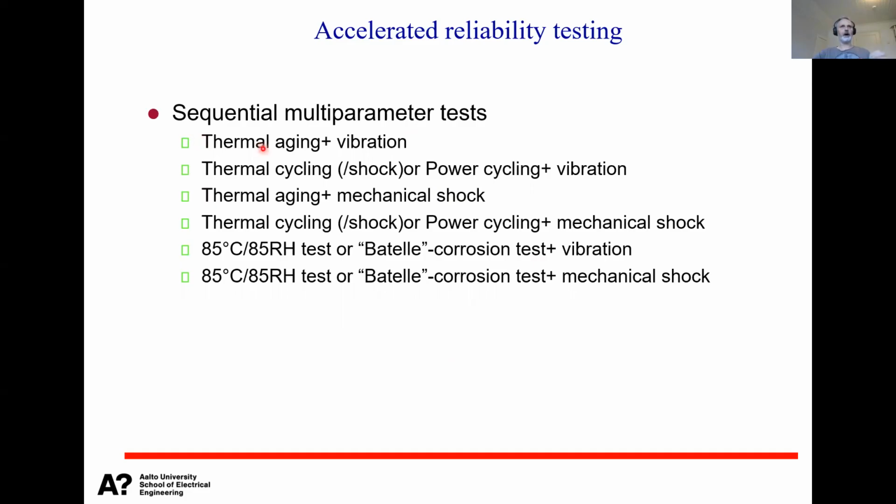Then you can monitor how the structure is evolving during thermal aging, and then you can see the effect of this microstructural evolution in the actual mechanical loading. This is what we are doing in our research project on a daily basis: we manufacture certain bonds, put them in the furnace, and then measure the mechanical strength, like tensile strength, in virgin condition as bonded, and then after certain aging treatments.